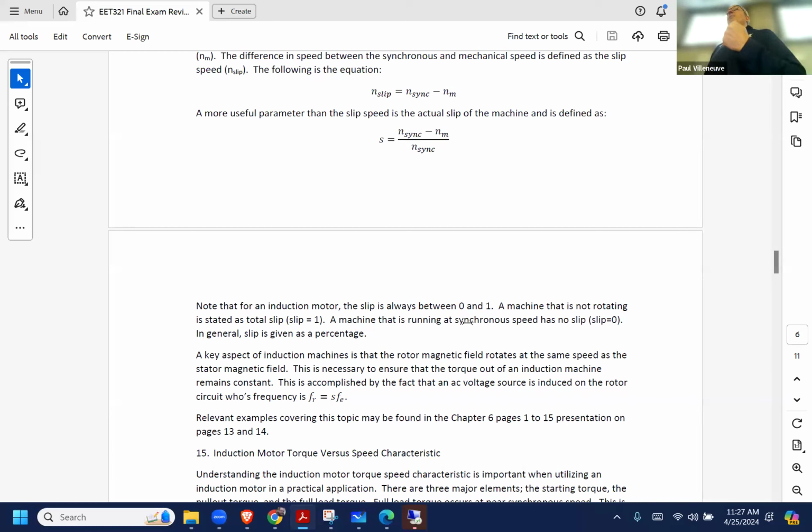And that allowed us to expand our understanding of, okay, well, how does this induction machine work? Because we know to get something to rotate, or something to move in general, we need a magnetic field that has a north and a south and either repelling or attracting another north-south. So we already talked about how we generate a stator magnetic field because of the currents that flow in the machine. It's the same thing over here. We have that same stator part, but the rotor is different. And the rotor will get its current or magnetic field from current flow that is induced from the stator circuit.